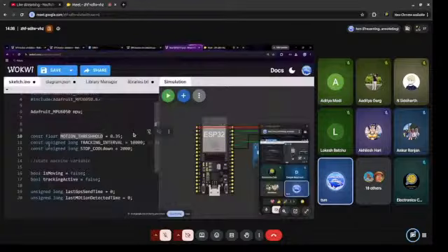After every individual 10 seconds, the tracking is done. It gets the value and computes it. Another constant, log stop cooldown: the device must remain still for 2 seconds, and only then is it considered as not moving. This prevents false stopping because of any tiny vibrations.